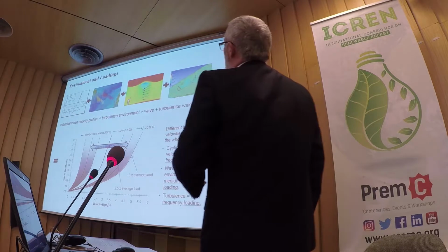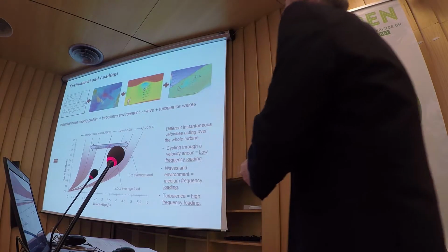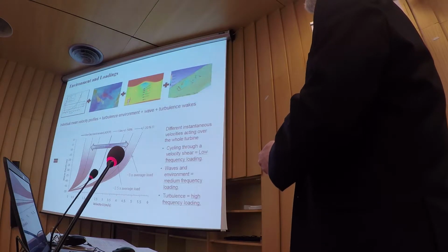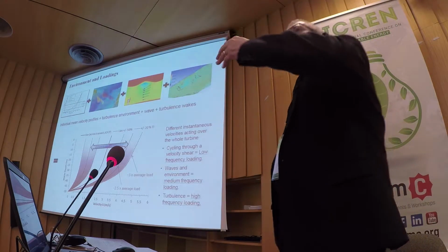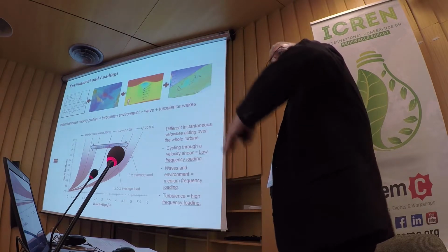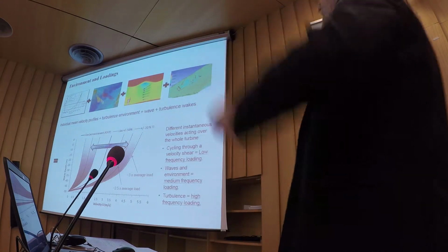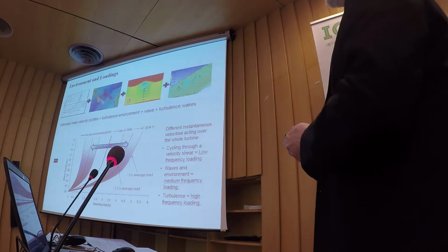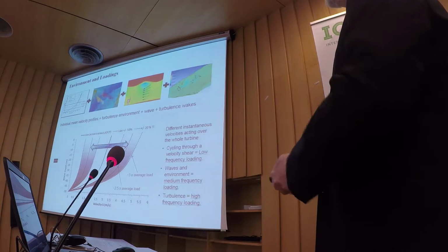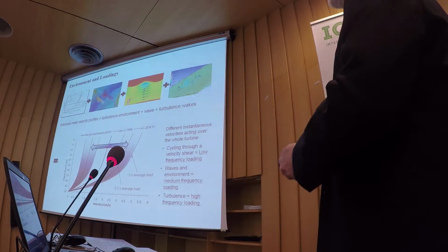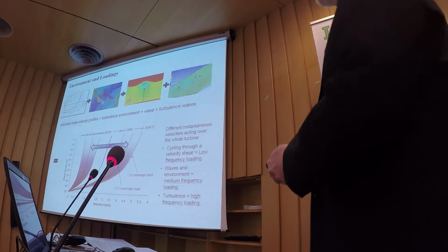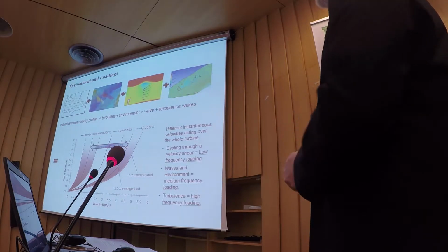Then you've got waves. Yes, you get accelerations and decelerations as a result. You also get this variation in the angle of the turbine, the upstream velocity component, which will be fluctuating itself up and down. And then, of course, the wakes. So you can measure your average velocity. Then you've got to take into account that it might be hit by larger scaled events. And then you've got turbulence on top.